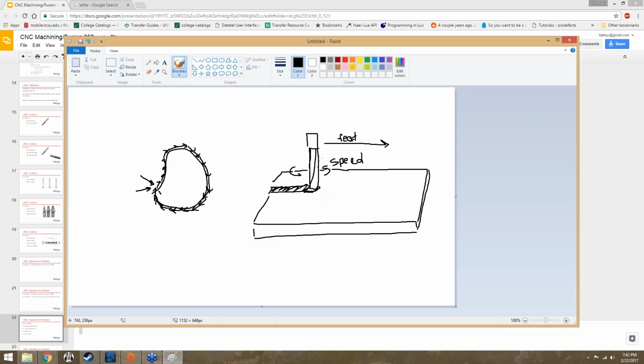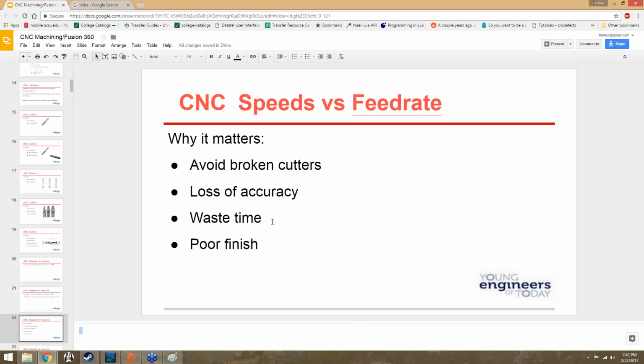In addition, the faster a machine has to move in order to make a cut, you do introduce some inaccuracies into it. On top of that, if you move fast enough, you run the risk of actually moving the material it's working with, which would definitely lower accuracy.